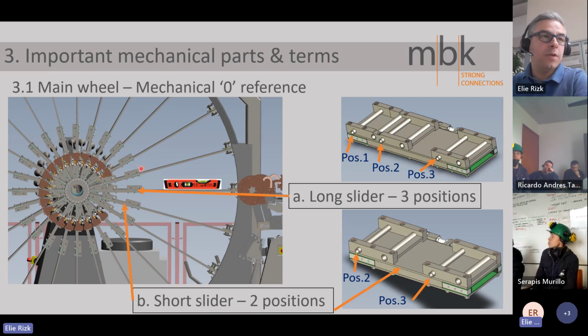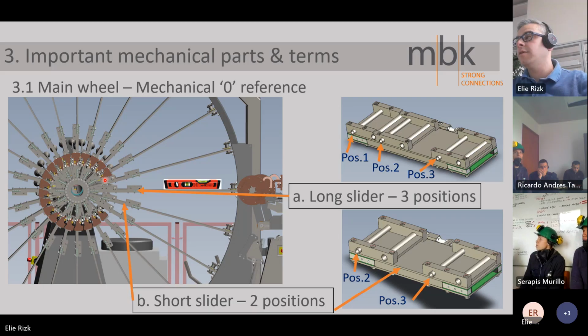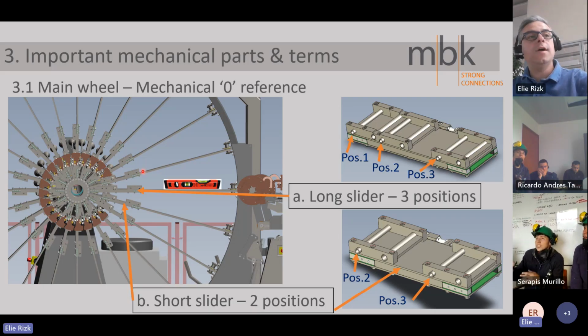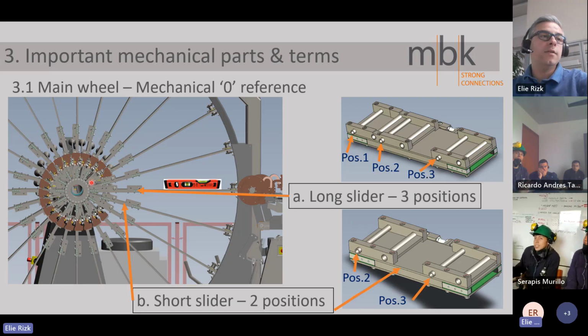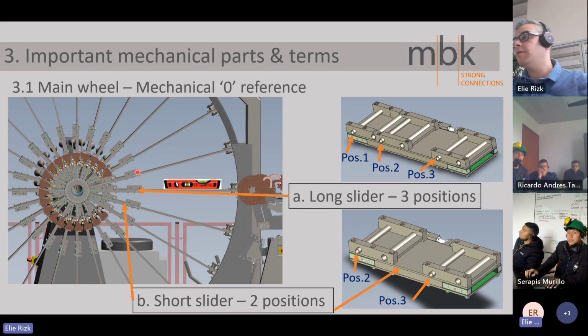So the slider is one mechanical part together. If you put the welding angle here, then you cannot reach the biggest diameter. But if you put the welding angle here, you can reach the biggest diameter, but you cannot reach the smallest one. So this is normal when you move from a big diameter to a very small one, then you have to change the welding angle position.